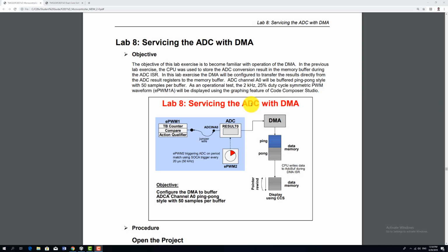In order for us to use the DMA, we need to assign a DMA channel. This DMA channel is used to communicate data between the peripheral device and system memory. Ideally, DMA can read data from the different registers. This involves the ADC, the transfer to or from memory blocks, the IPC, the EMIF, and others.